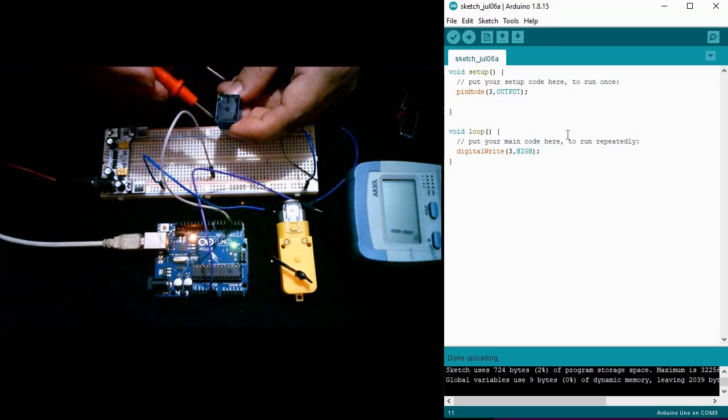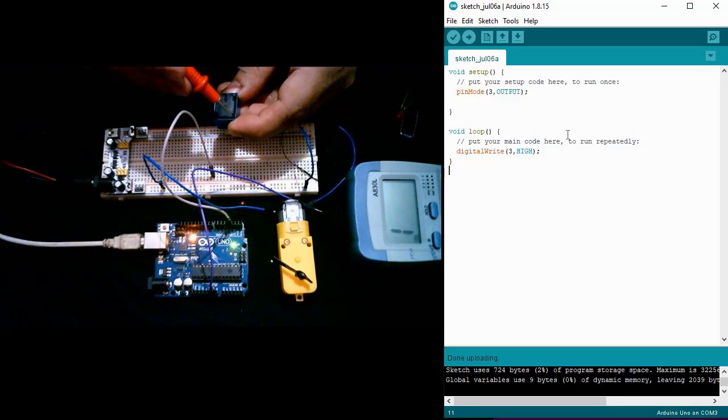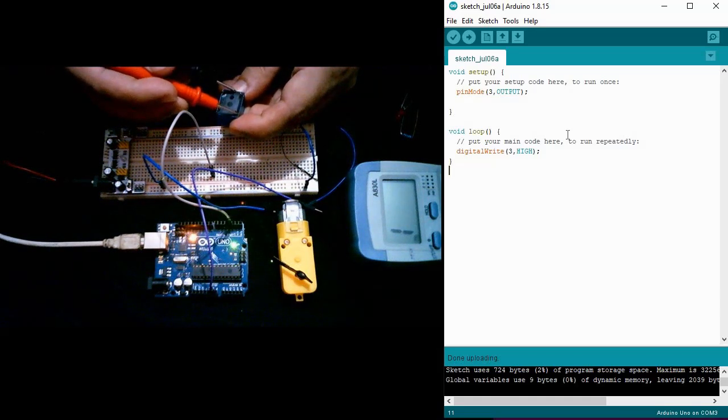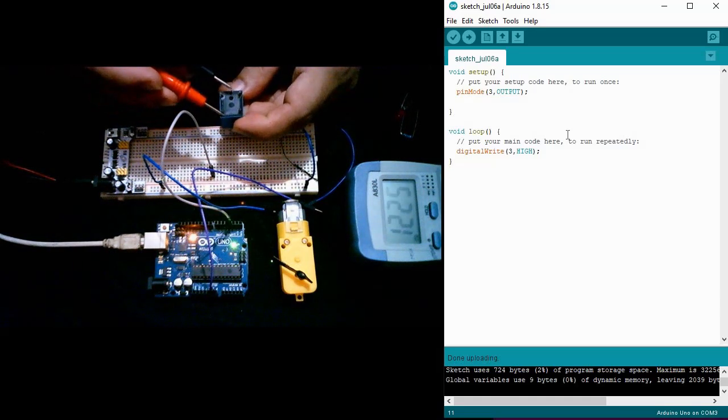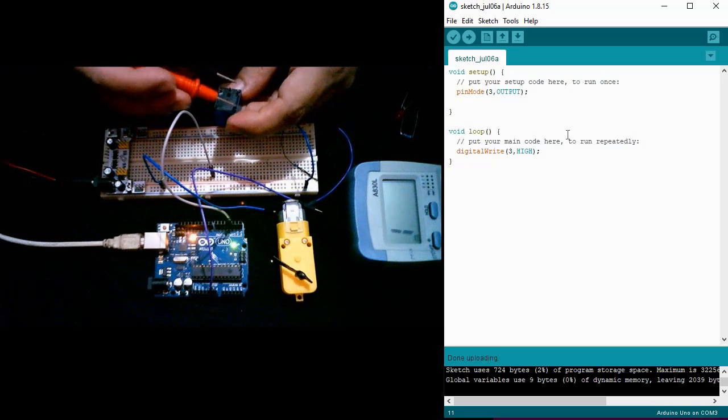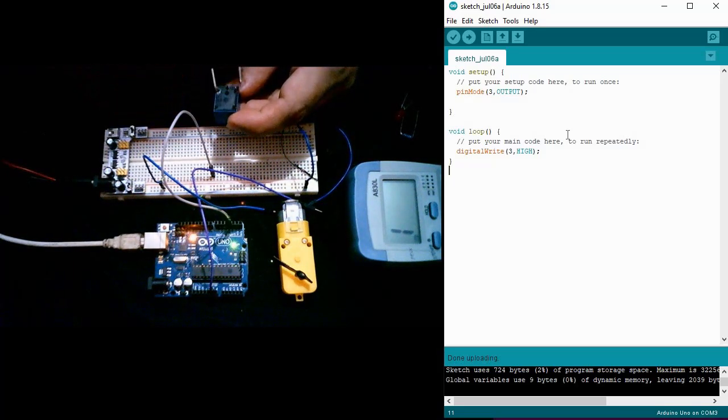It means these two are normally closed and the one on the other side is normally open. So this is normally closed. You can see the same value on the resistance, a very low resistance, unlike here. Then this is also the coil resistance. So you have their resistance.